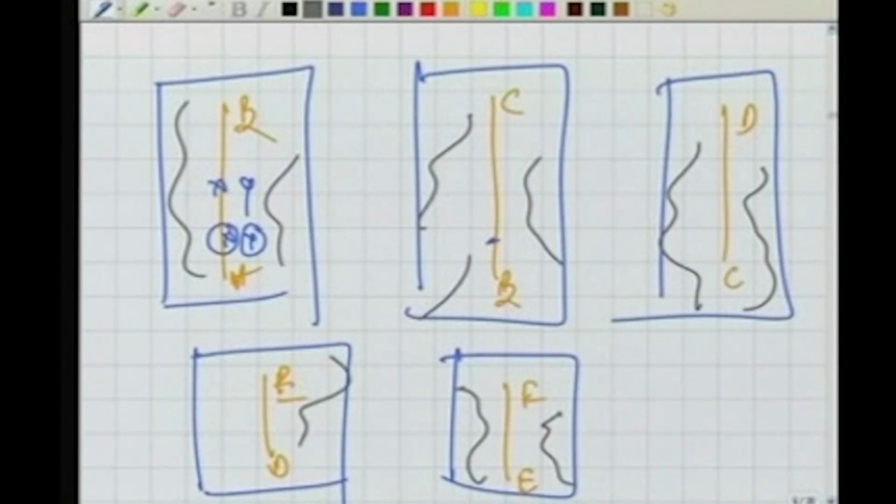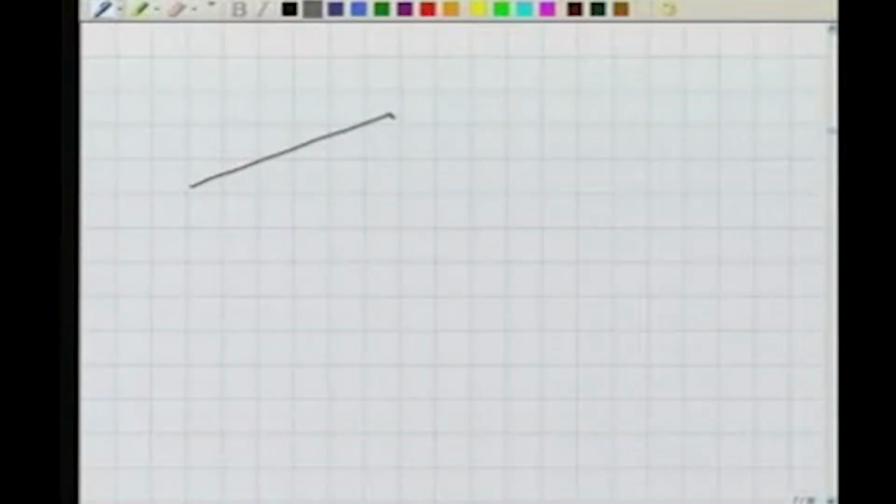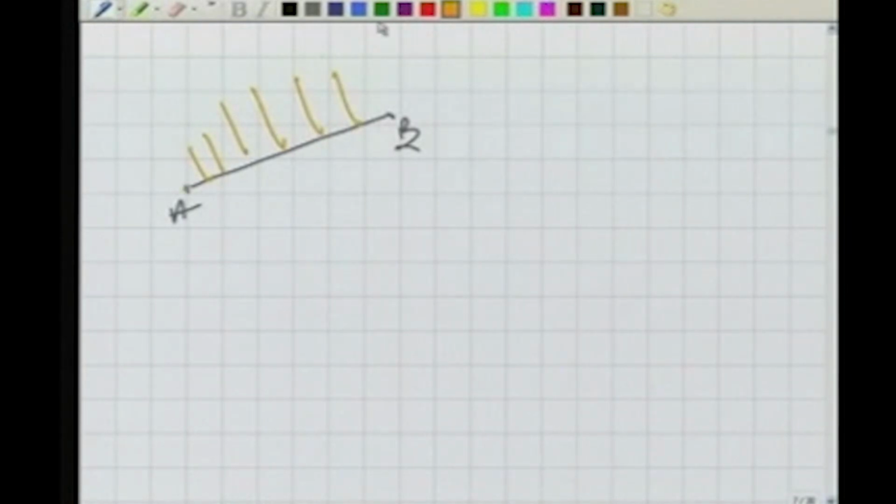We know how to produce it. Now, using all these pages of the field book, we can combine them together in order to make the map. Well, I start with line AB. I know that I have taken the offsets, and the offsets are certain values here, and I join these in order to make my boundary.